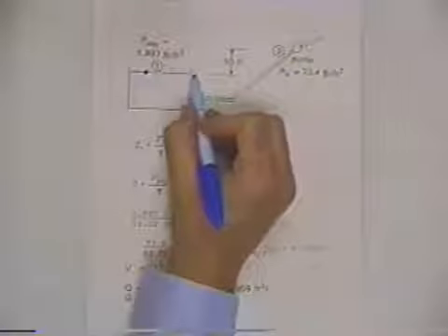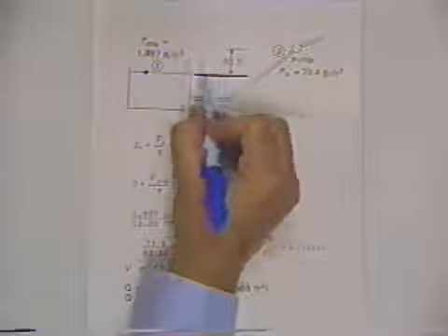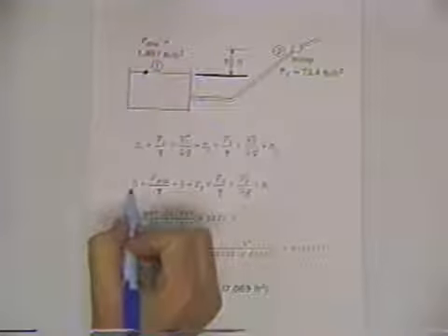So here at the surface of the sump reservoir, we need to set the datum. That's a convenient place to set the datum, so that's the horizontal datum. And so that's going to let our elevation head at point 1 be 0. And when we worked these problems before, we said the pressure head was 0 because we were using gauge pressure,